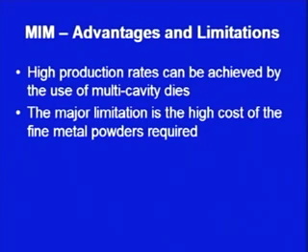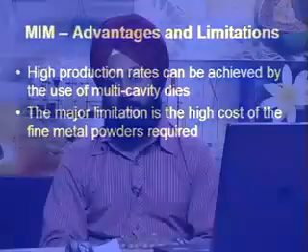In rolling, it is not the molten metal, it is the powder mix or the product mix, which has been made by blending the different powders together with the lubricant, that is passed through the rollers and we get a sheet of the PM part or the powder metallurgy part. So, this sheet can be made use of in making the coins that we use as currency or for other operations. In case of extrusion, the powdered metal particles are pressed with the help of a ram and are extruded out. So, these extruded green compacts can later on be sintered to get the final product.